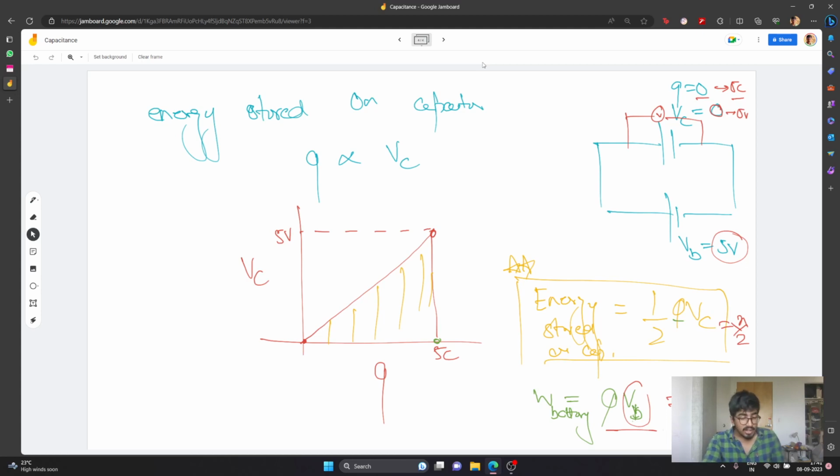So the question is, where does this half of the energy go? We say that there must be some resistance in the wire. You will see that those wires get heated up at the end. So that is where half of that energy goes. Only in the process of transferring energy from one place to the other, you have lost energy in the process of charging up a capacitor.